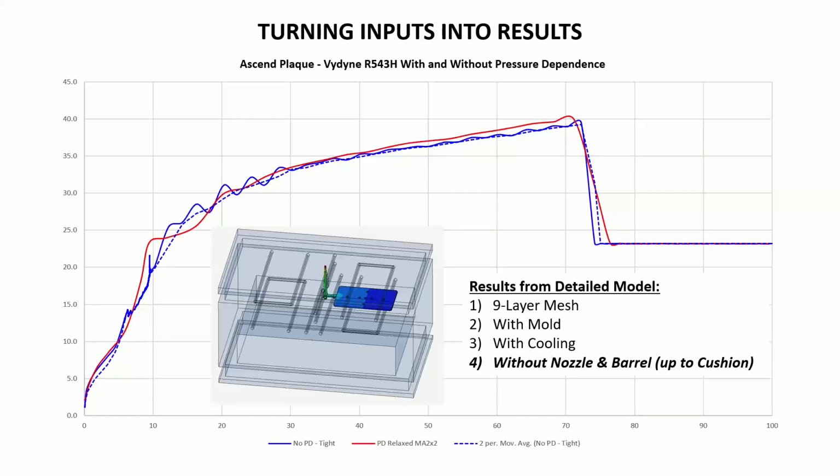So a couple of megapascals in this case. In other cases, I've seen it take 4%, 5%, even more. Some polycarbonates, significant percent difference. So again, that's part of my Antec paper. So if you are part of the Society of Plastics Engineers and you attend the online conference and find my paper, you'll see my presentation there regarding that and the fitting of Williams-Landel-Ferry coefficients.